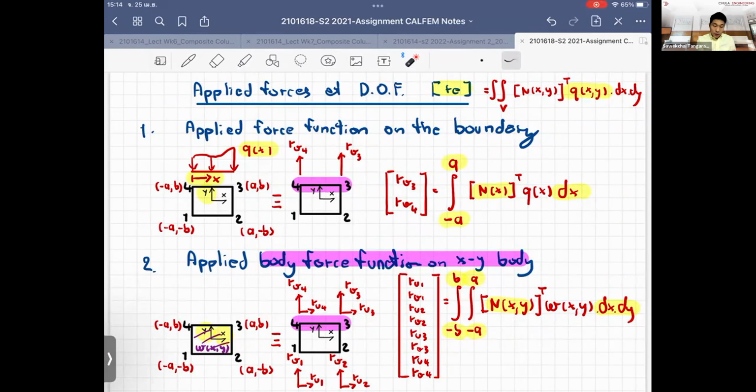You need the force matrix as well. If you have the force applied at the boundaries, and it's a linear force, it's easy because you can just simply use the average area between the nodes and multiply with the values of the force.